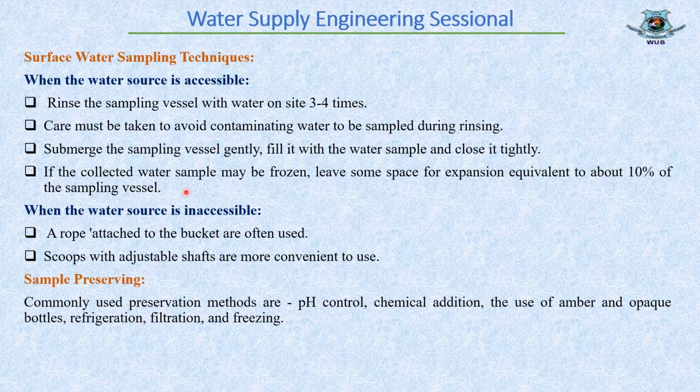If the collected water sample may be frozen, leave some space for expansion equivalent to about 10% of the sampling vessel. And when the water source is inaccessible, for example water sources like a dug well, we have to take a rope attached to a bucket to collect the water. Scoops with adjustable shafts are more convenient to use.